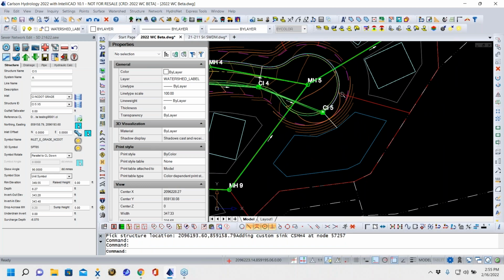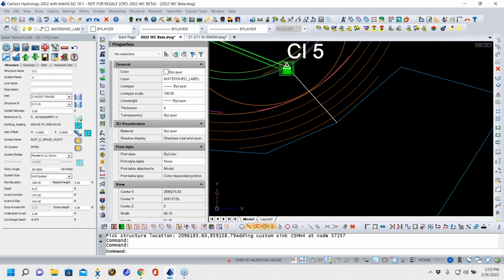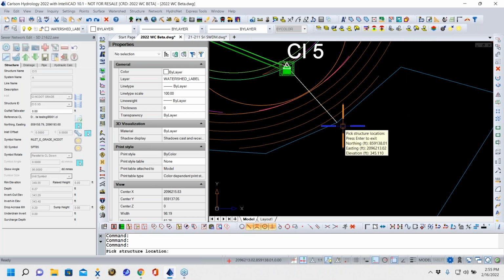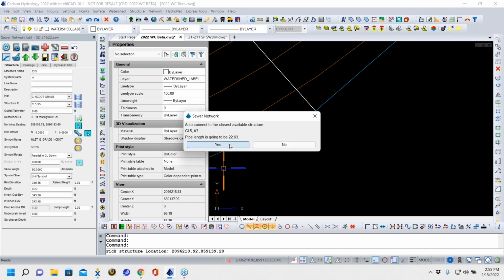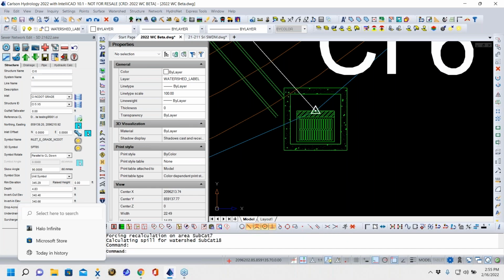Okay, catch basin one is a low point down here in the bottom. I rotated the cul-de-sac to force a low point down here to my detention pond. And now let's go ahead and throw in our flared in section. So I am going to snap to the end. Yes, this is fine, but this does not have an inlet. So we got some things to change.